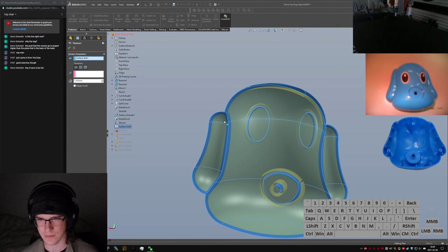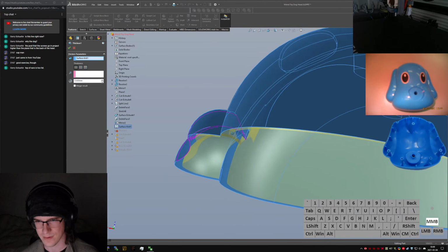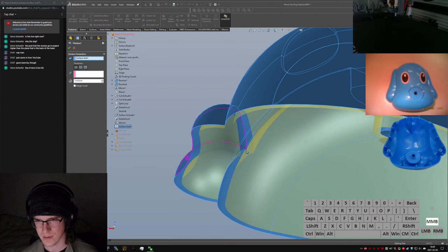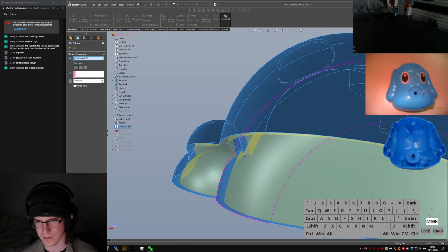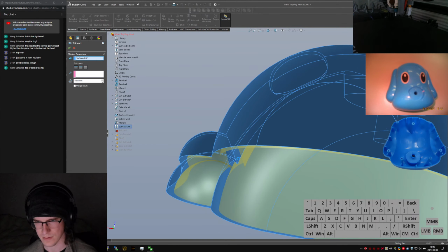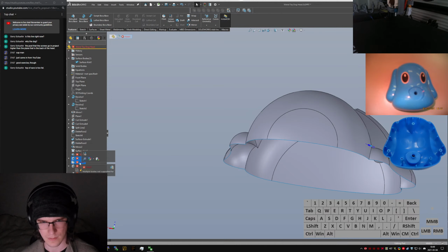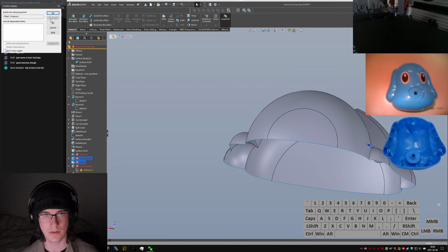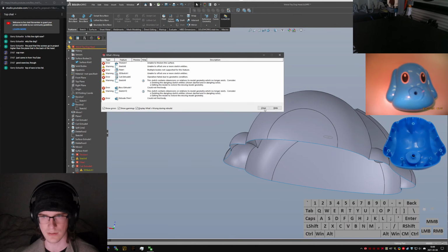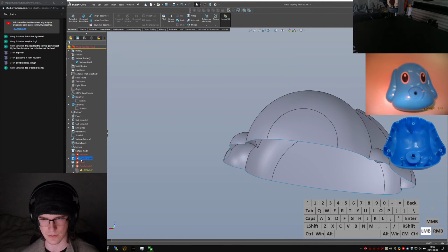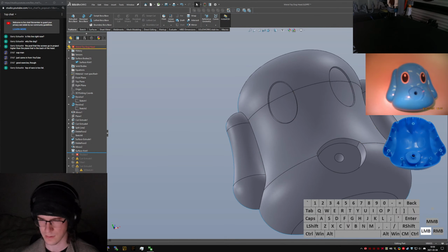Unable to thicken the surface. Why, though? Oh, I see. Because suddenly it gets too sharp down there. Okay, well, if I bring this fillet up... Actually, I'll delete the fillet. Ooh, nope, don't delete the cut extrude. I'm gonna come up here to right after the surface knit.